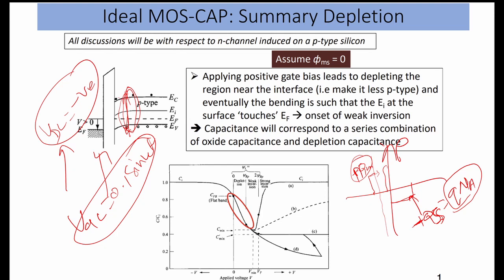So this is in the depletion case only. There is no inversion. No inversion means there are no electrons at this point; n is less than p in this region. So this is the depletion only. There are no charge carriers actually in this region, because it is depleting the carriers at this junction. So this is the qNa.